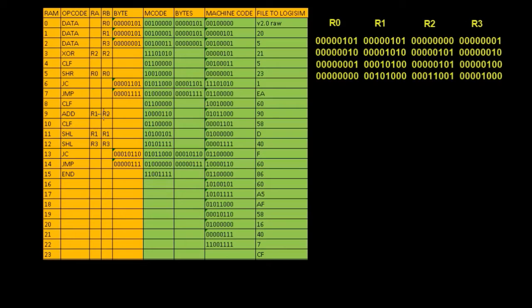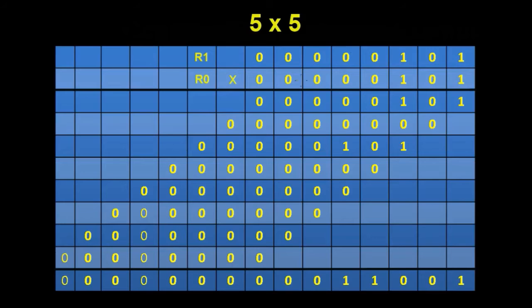Okay, so we've got down to this point here. It clears the flags again. It goes in and shifts left the value of R1 and puts it in R1. So that's taking this thing here and shifting it left. When you shift this number left, in effect you're multiplying it by 2. So it's equivalent to working through the shift left here whenever you do the normal multiplication.